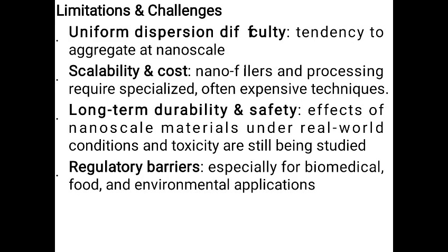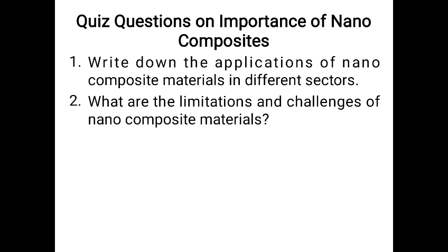Limitations and challenges of nanocomposites: uniform dispersion difficulty, that is the tendency to aggregate at nanoscale range. Then scalability and cost: nanofillers and processing require specialized techniques and it often seems to be a little expensive. Long-term durability and safety: effects of nanoscale materials under real world conditions and toxicity are still under study. And regulatory barriers, especially this is in the field of biomedical, food and environmental applications.